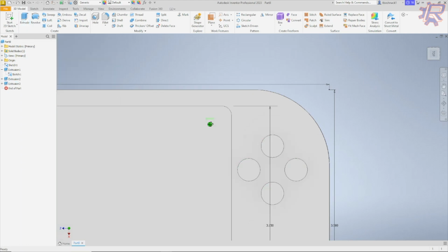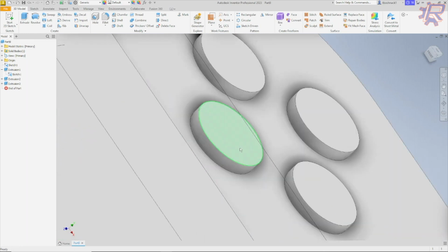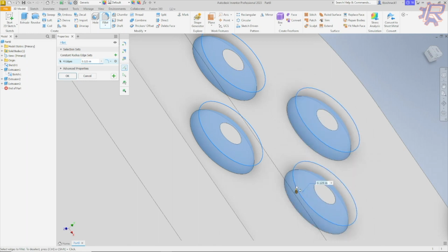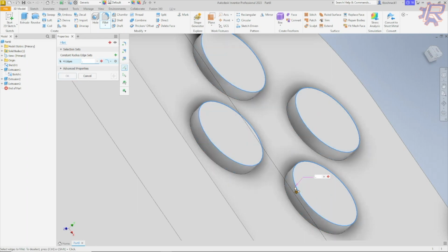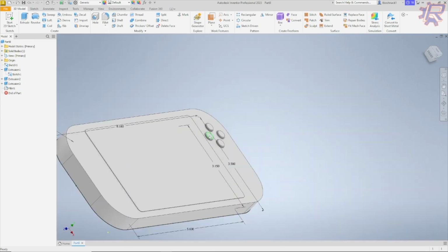And once we have them extruded, we can do something else to make them rounded, because the buttons aren't usually having a hard edge like that. So we could use a 3D fillet tool. And it basically works the same exact way as the 2D fillet tool. Again, you could change the size. Let's make this, I don't know, let's use 0.02. And then you have that nice curvature.